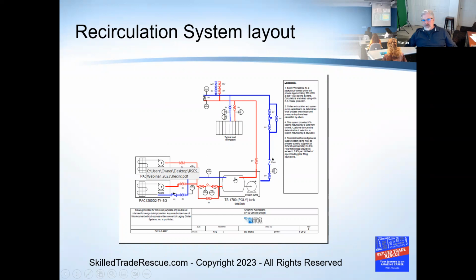It's mixing. Well, what immediately is going to happen, and I may be going off in the weeds here a little bit, both of the controllers on these 2 chillers are going to say, whoa, wait a minute. My set point was 45, and I'm seeing a rapid change here. So this extra capacitance gives some time for these compressors to stage up or load up, depending on the type of compressor we have in there. And again, the benefit is that the customer doesn't see the degradation. So that's really the big thing.